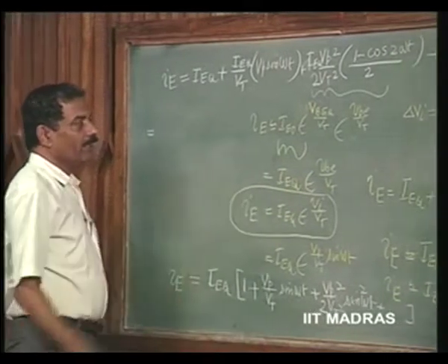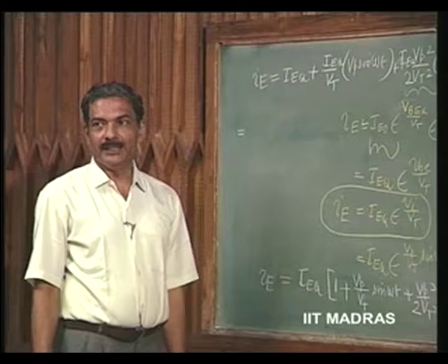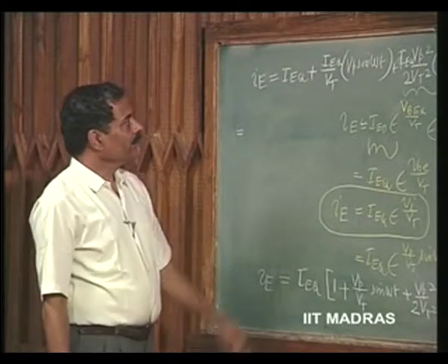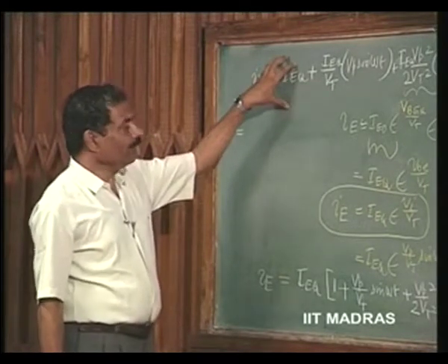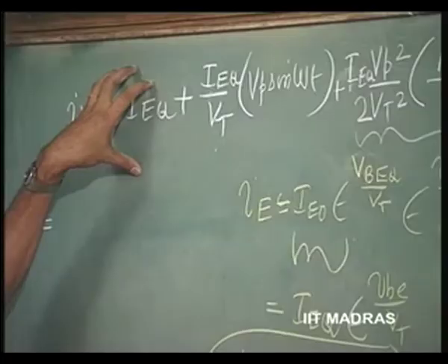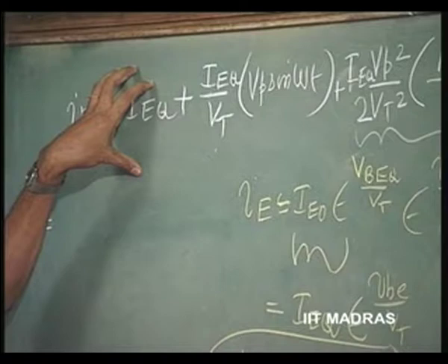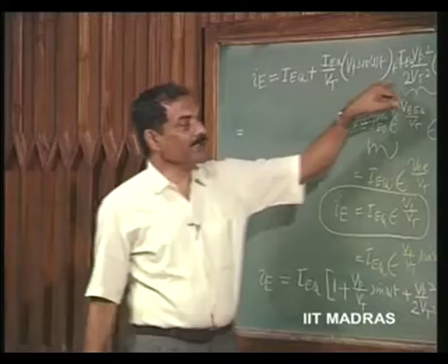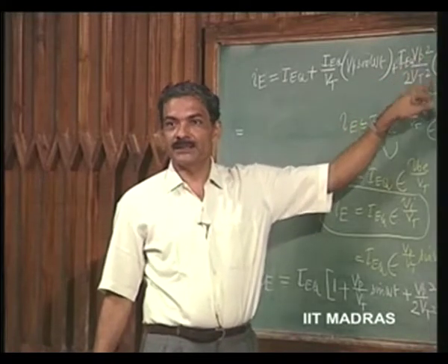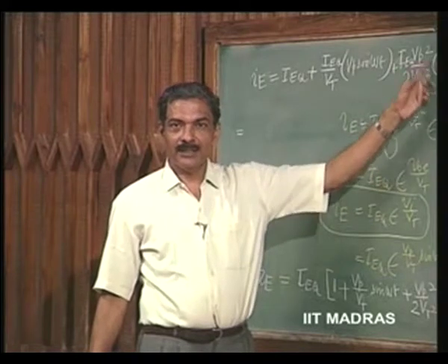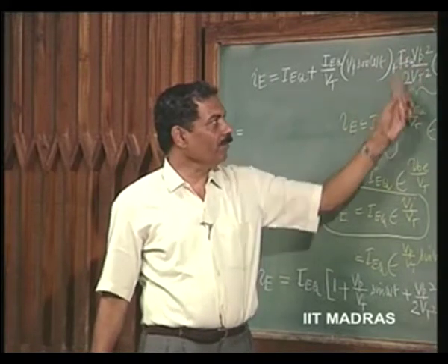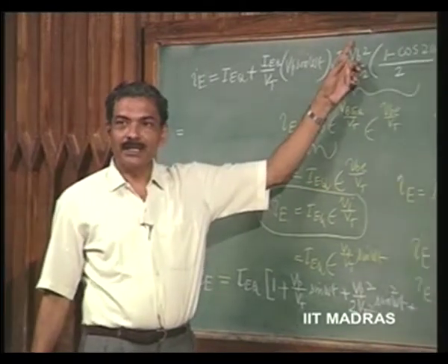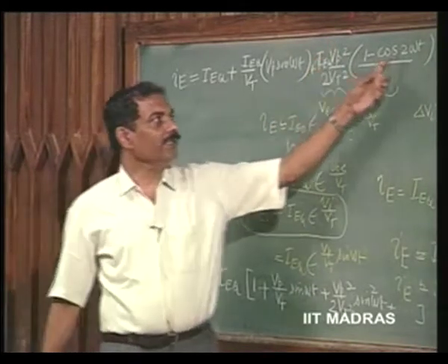This is one way of testing the linearity. If an amplifier is biased at IEQ, right, when you apply a sine wave signal, pure sine wave signal, the bias point, DC point itself shifts, okay, and the amount by which it shifts gives you an idea about the distortion.